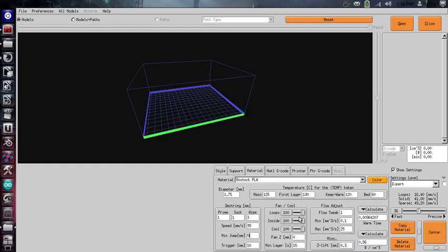These are good values. Fan, if you have a small fan, just leave it on all the time. If you have a lot of cooling, then you're going to want to play with this to turn it down, because as the material cools, it curls, and adjusting these values will adjust your amount of curl if you have adequate cooling. Otherwise, just turn these on all the time, basically.